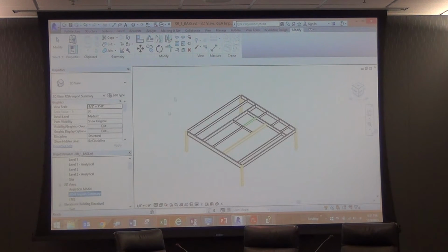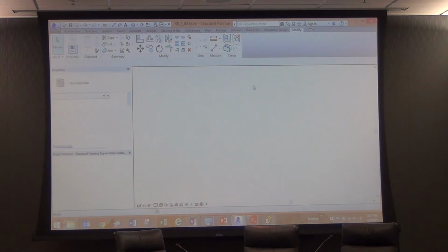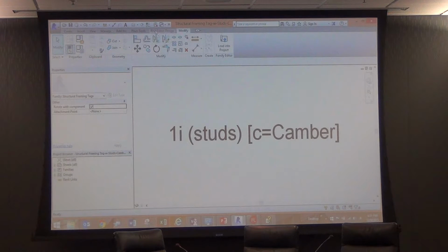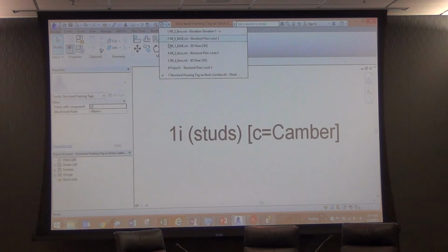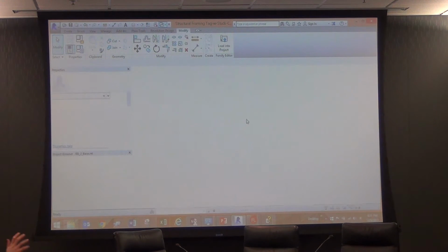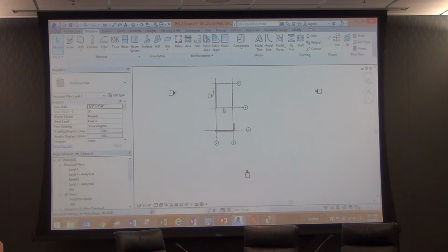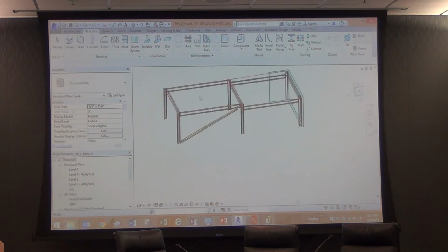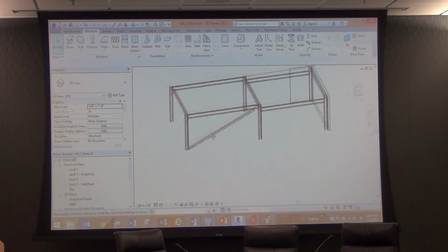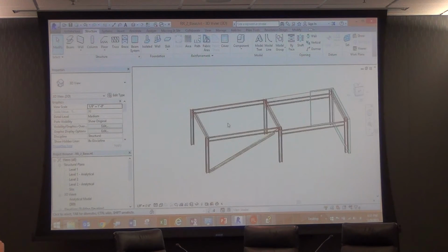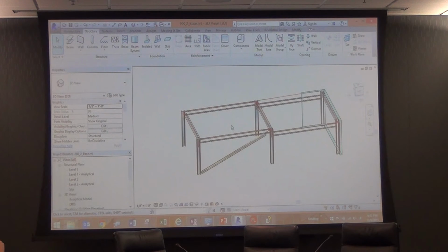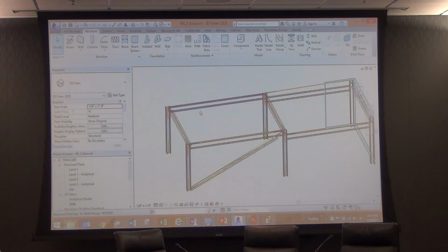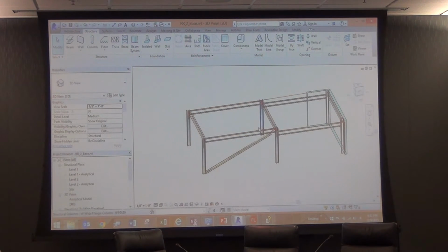So there's that one. Now the next one, if nobody has any questions on that one, I guess I'm going longer than an hour almost here. Let's go to this structural plan. The thing that I want to emphasize is the importance of the analytical model and some of the things that RISA does or that happens within Revit that makes it not correct.